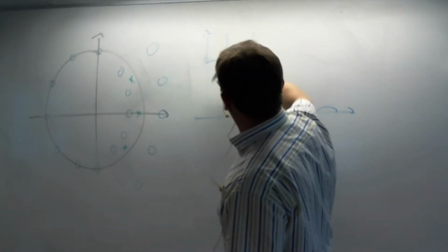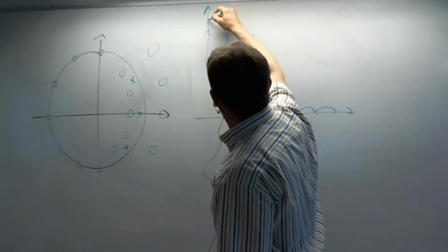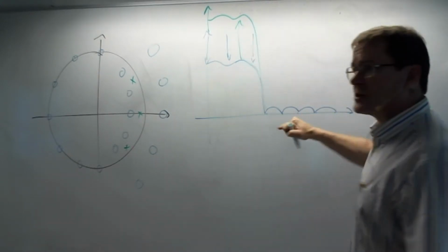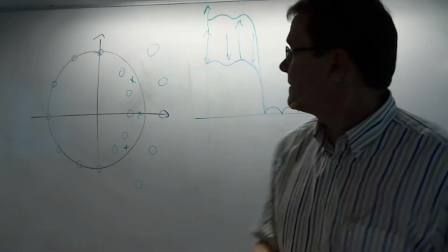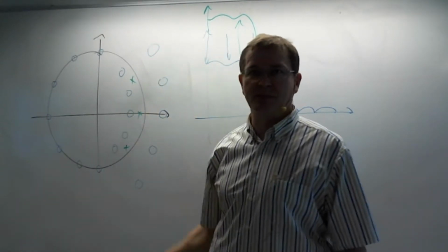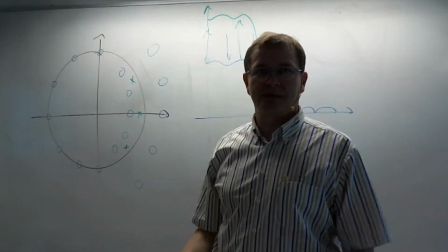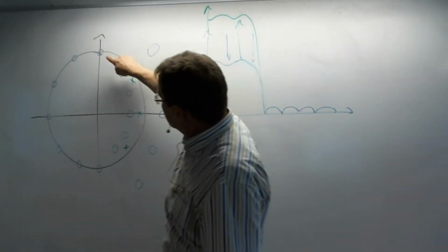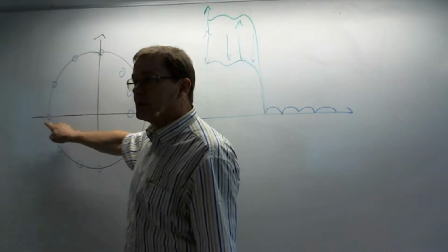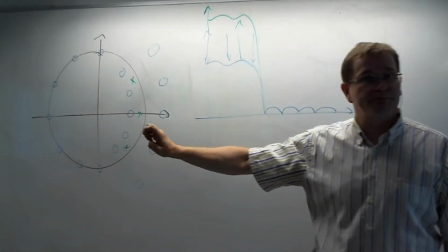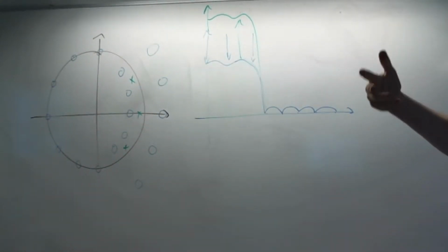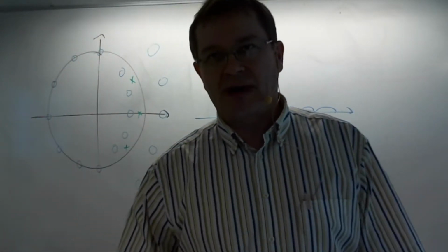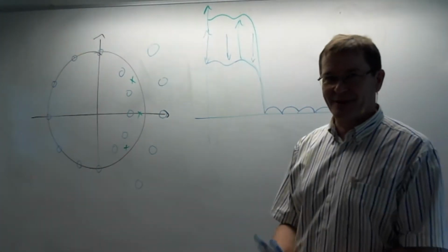Then you get more gain, but at the same time better stop band attenuation with fewer calculation points. It's quite obvious when you look at this, since every one of these requires one multiply accumulation. The number of zeros and poles is the same as the number of calculations plus one.